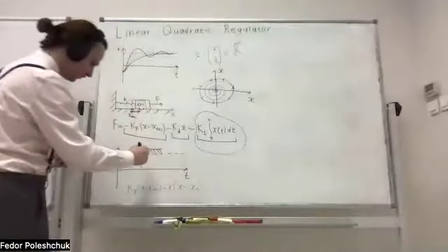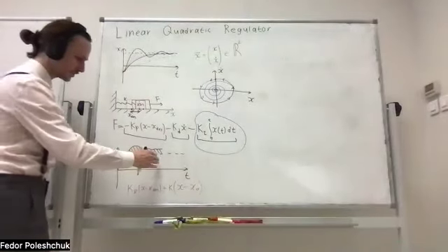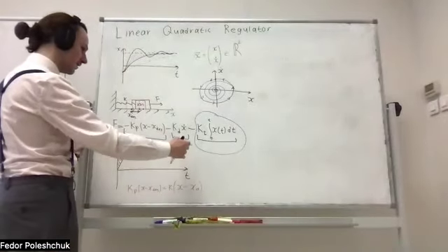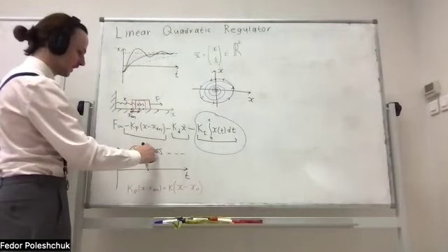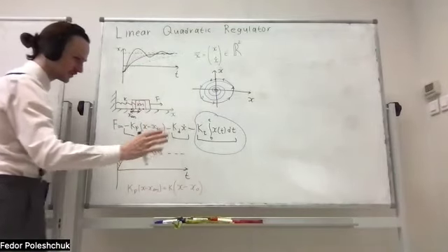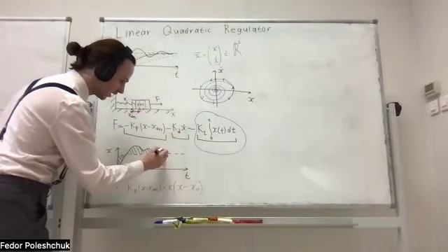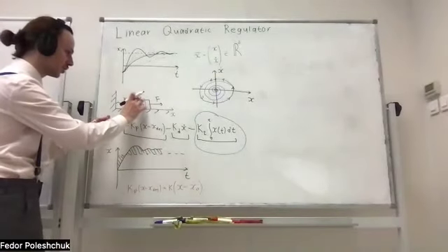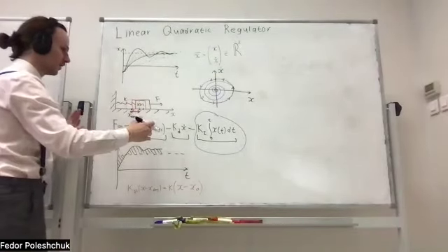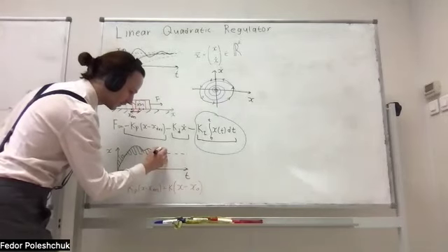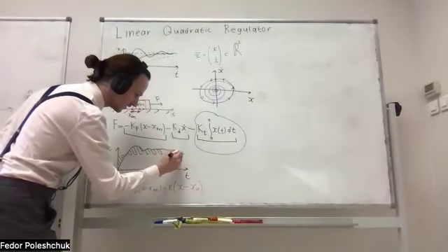What will happen is that as time goes, the integral term grows, and the force increases slowly over time, which means that the block will move to the left, compressing the spring more and more, but the deviation will decrease over time.